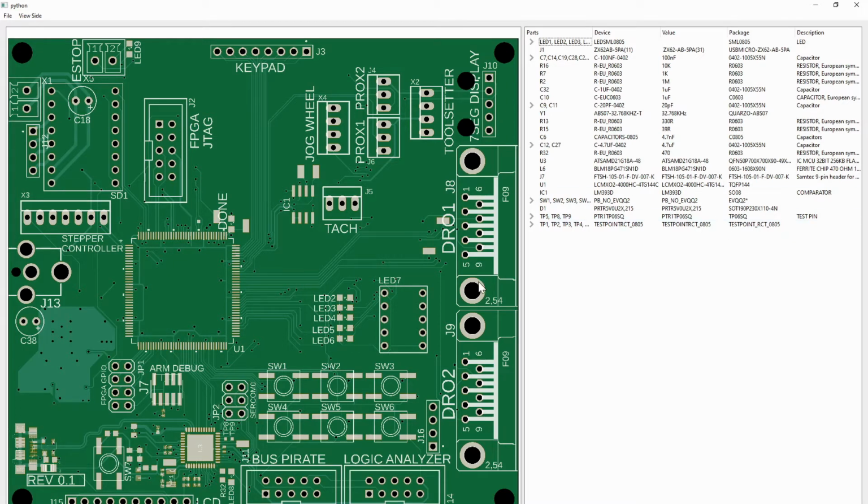Here we get the tool up and running, and for starters you can see that there's a relatively realistic graphical rendering of the top surface of the board. In the right-hand column, there's a list of parts from the bill of materials. The key thing to note here is that this list has been filtered down from the full bill of materials to show only parts that are surface mounted and only parts which belong on the currently visible side of the board.